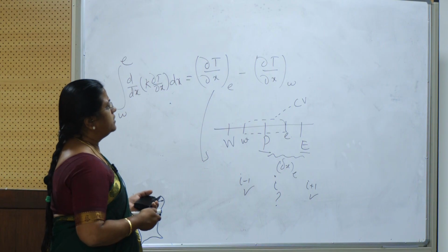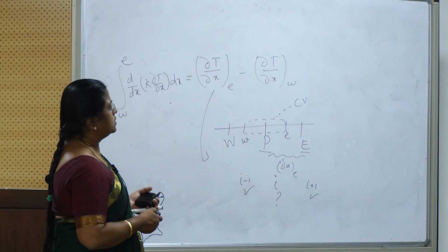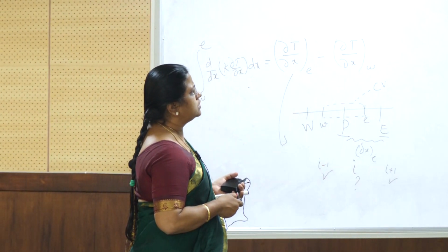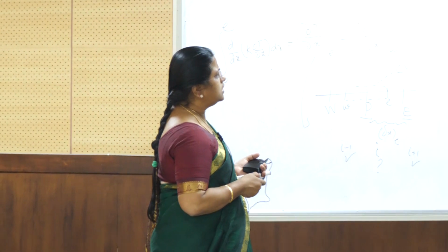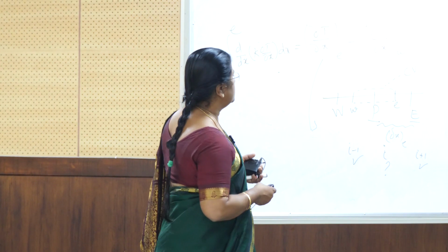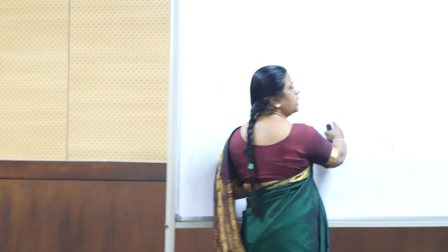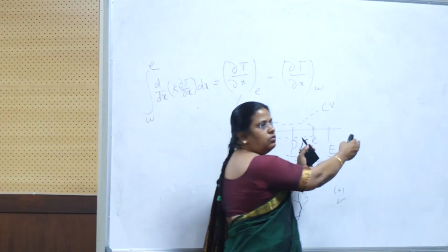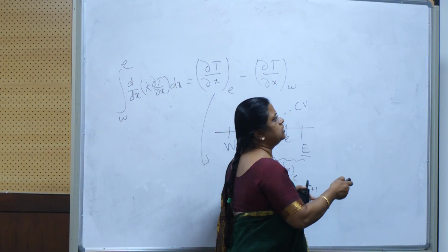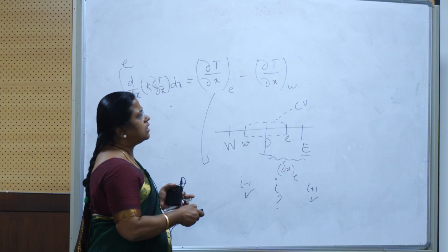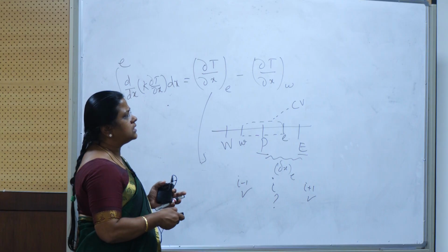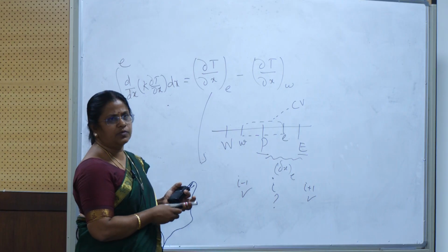Many examples are given here. This is what you see here. It will be consistency at a control volume face. Whatever comes in must go out. When a face is common to two adjacent control volumes, here we have one control volume and another control volume will be here. Again, I can take I here, I minus 1, I plus 1. The flux across it must be represented by the same expression in the discretized equations for the two control volumes.